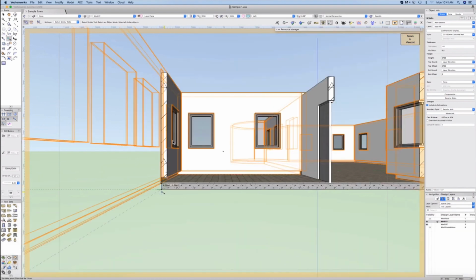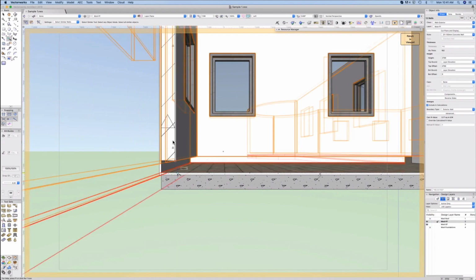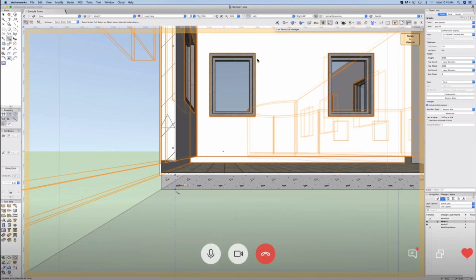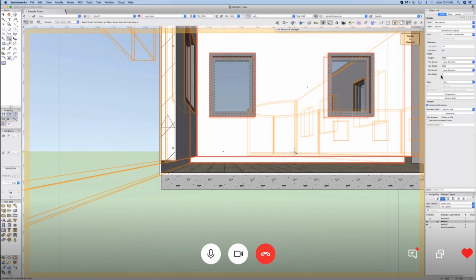What we forgot here was the slab thickness, not the tile. Yeah, so there's kind of two ways to do this. You either take those first four walls and move them all down a bit. So if you go to the bottom offset value over in Object Info, just put minus 150. No, not that one. Cancel that one. Just put minus 150 for the bottom offset value in. No, not that one. Minus 150.